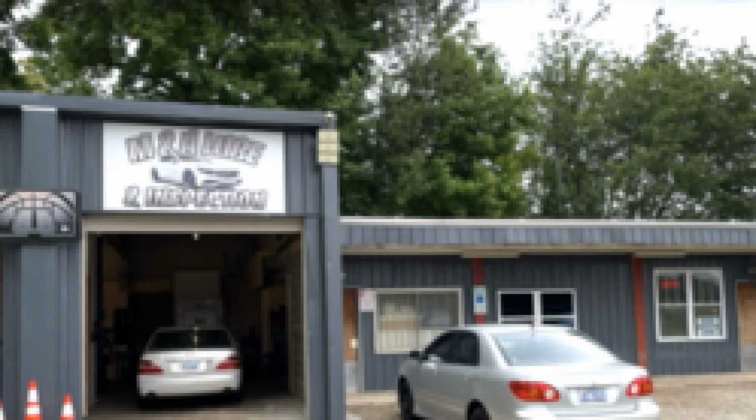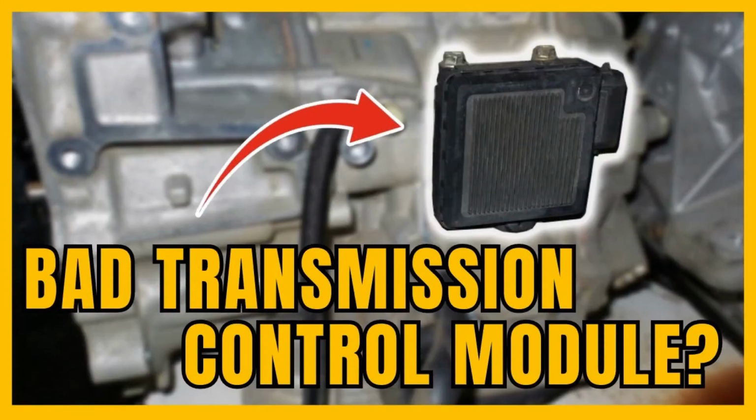Causes of the error. P07A6 could mean that one or more of the following problems have occurred: internal friction element worn, possible short circuit or wire breakage, contamination or low level of ATF transmission fluid, a problem causing uneven rotational speed, e.g., low tire pressure or jammed brake, inconsistent tire sizes. Sometimes a faulty PCM or TCM module is the cause.